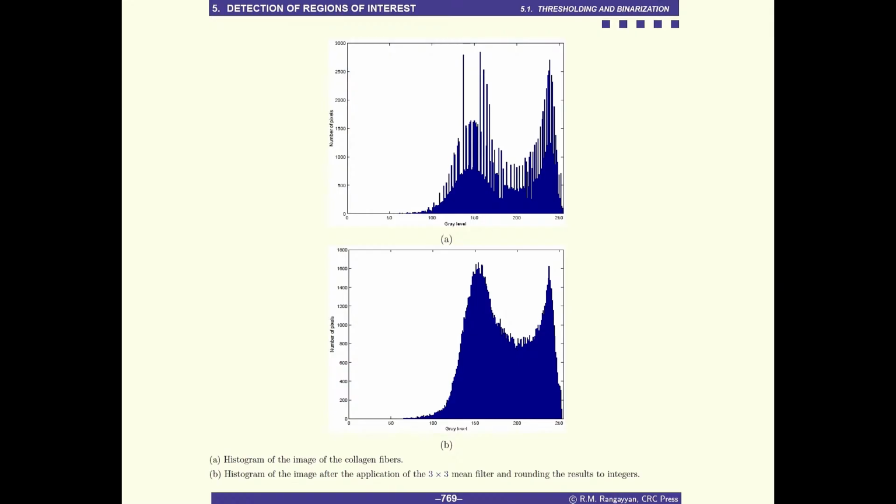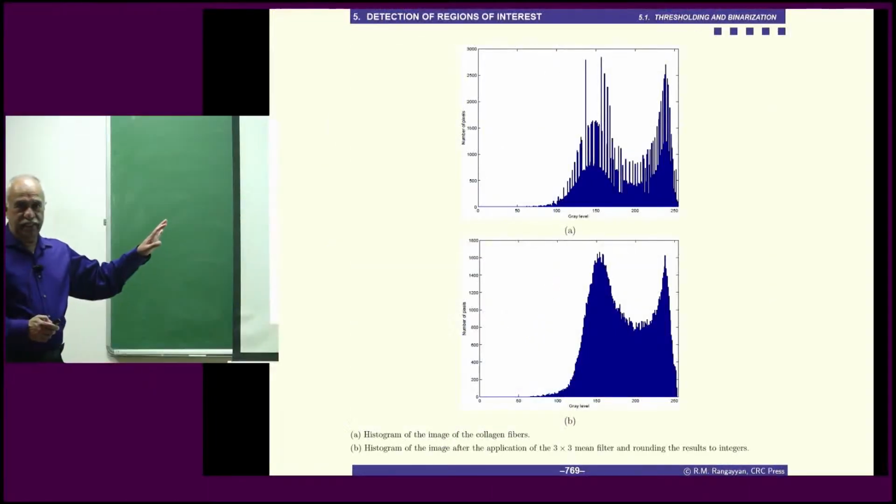You get this, where this distribution is continuing and that distribution started somewhere there. There is so much overlap. Still, optimal threshold will say, find something in this valley between the peaks. And if you can find a valley, then we can minimize the artifacts of misclassification of background as object or object as background. So that is basic thresholding. I'll discuss other thresholding methods later.